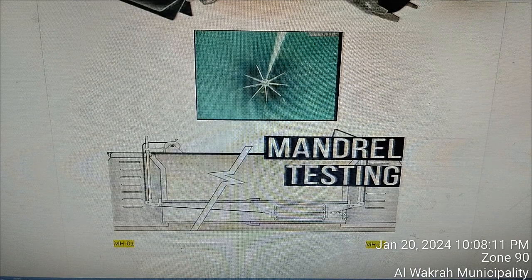workable. If any settlement is found, it is called deflection. The settlement normally occurs in the joint area, in this area. If there is any settlement, it needs to be rectified by digging out this portion and replacing the joint, or the whole length of the pipe needs to be replaced.